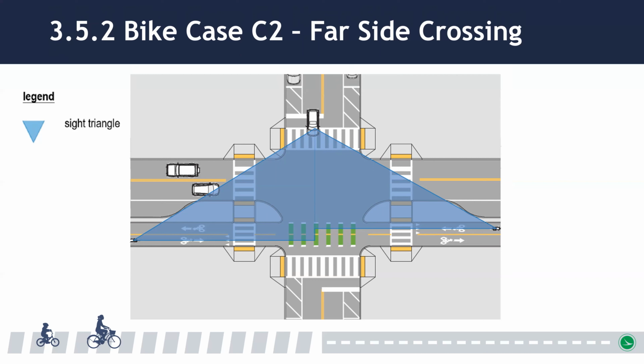As such, designers should consider the frequency of through movements at these types of intersections and provide either traffic control devices or adequate sight distance, i.e. minimum stopping sight distance, for bicyclists to see and react to a crossing vehicle and stop if necessary. It may be appropriate to restrict these through movements for motorists where traffic control devices or sufficient sight distances cannot accommodate this sight line.